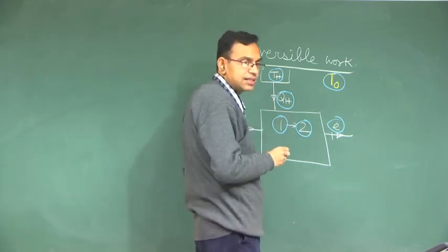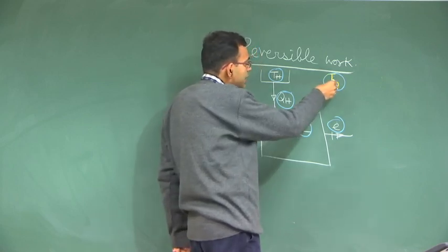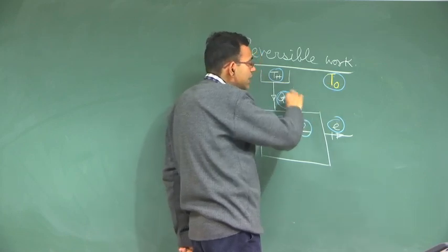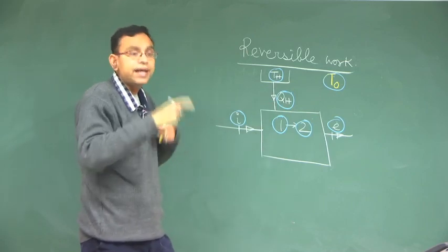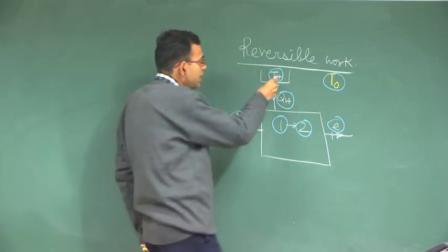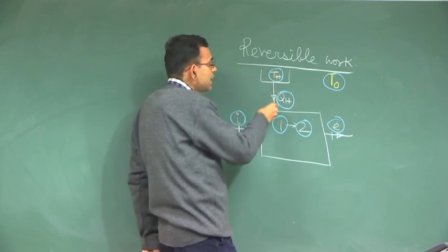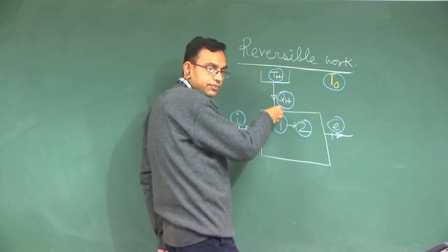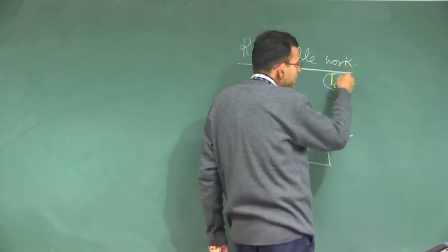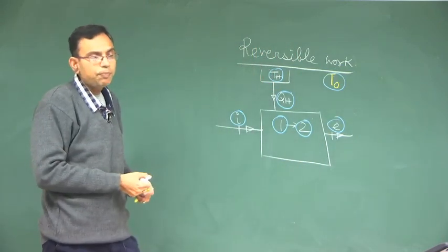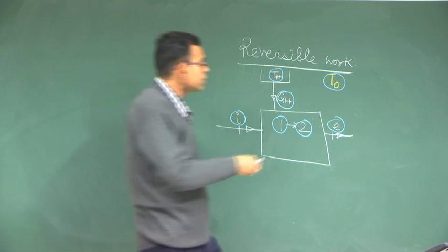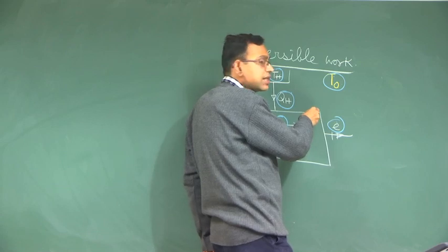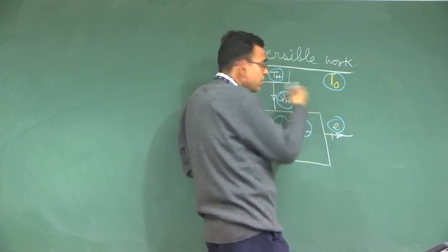One missing link here is that given that you expose this system to a surrounding, there is a difference between two terminologies, one called immediate surrounding and another called surrounding. This one is an immediate surrounding because there is an arrangement by which this thermal reservoir directly interacts with the system, but you have a broader surrounding which is the ambient. There is a potential of heat transfer by virtue of the temperature difference between the ambient and the system boundary. That is not given.